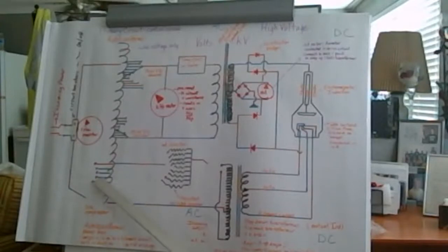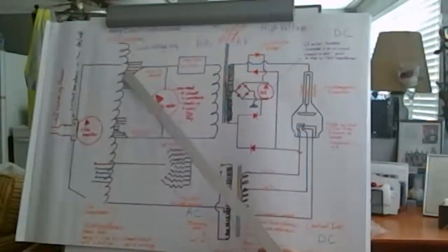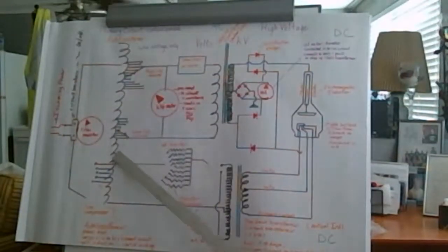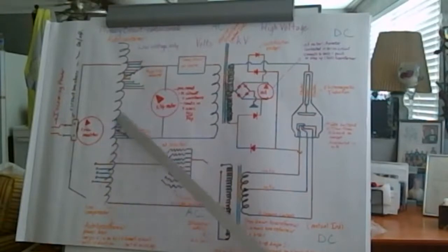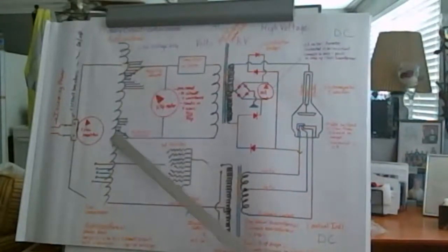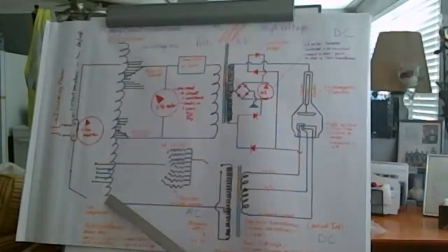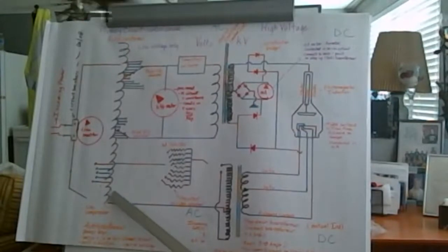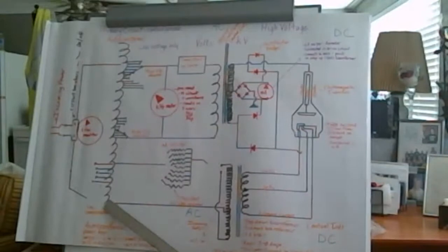And the line compensator, these taps, that's what they're called, these little lines with little dots at the end, come off of the far side of the auto transformer. This whole line coming down, all these windings you see, are the auto transformer, and that's considered the very first part of our circuitry to get power to it.